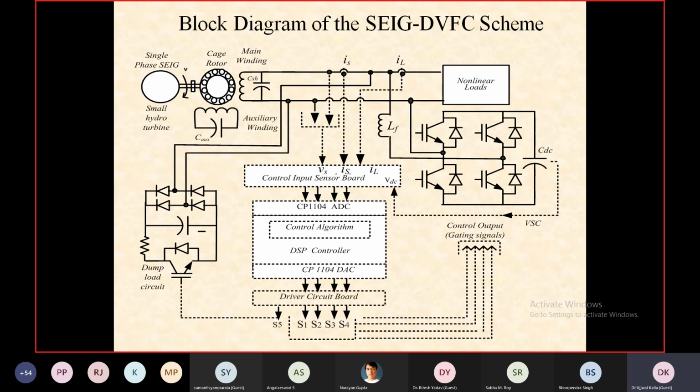But now I have the VSC, which can mitigate all the harmonic current injected by this single phase rectifier filter load. So all the harmonics injected by this dump load have also been mitigated by this voltage source converter. So it is still not creating any problem. But honestly speaking, it will increase the burden on this voltage source converter. So that will increase the rating of the voltage source converter. That is another thing. But I had a limitation in my laboratory at that time. This scheme I implemented many years back.